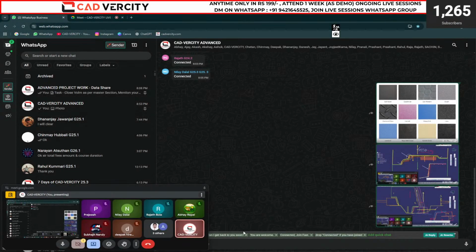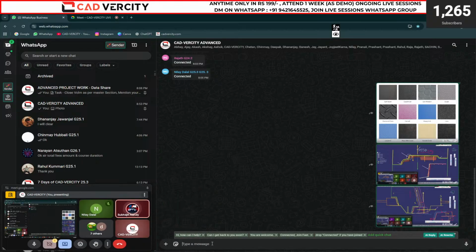The formula for pin diameter plus total length of undercut, and what the stroke should be. Then lifter calculation, undercut area, lifter length, lifter travel.